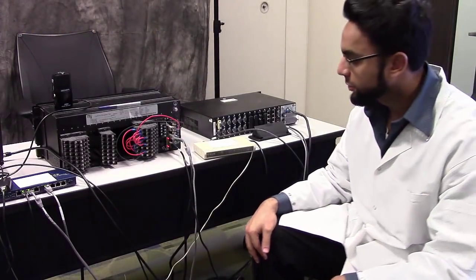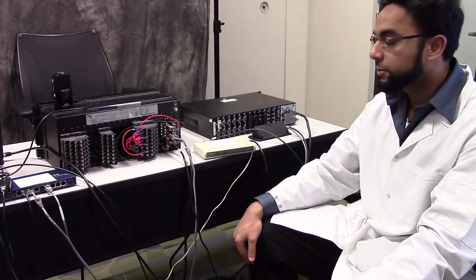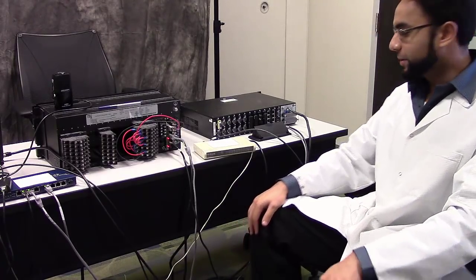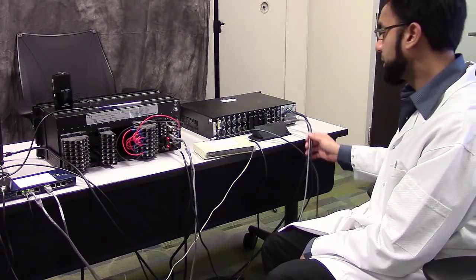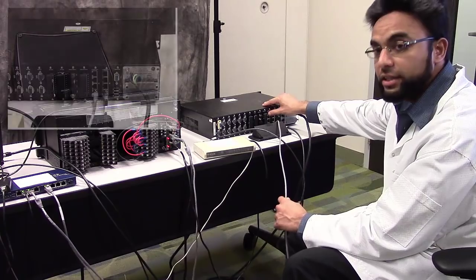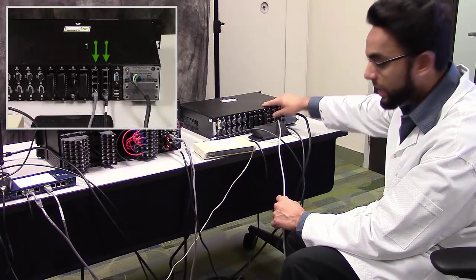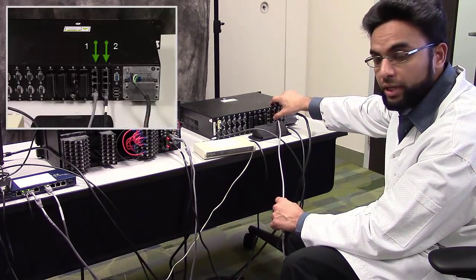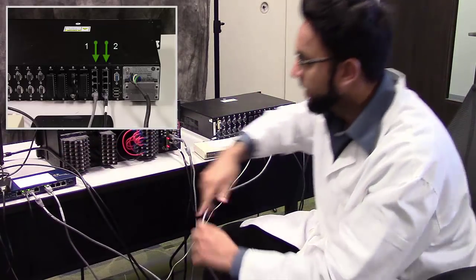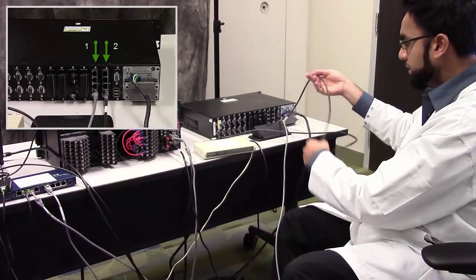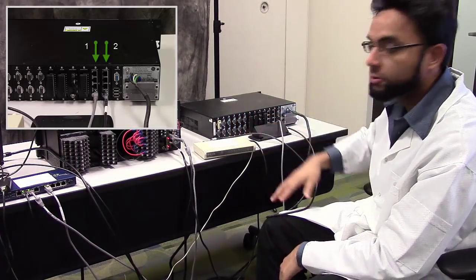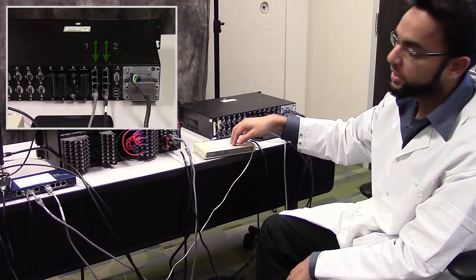Okay, now I'll show you the physical connection, how the D400 and the UR are connected together. On the D400 you have two Ethernet cards. This is Ethernet card 1 and this is Ethernet card 2. Ethernet card 1 would be connected to switch 1, and Ethernet card 2, which is LAN B of D400, is connected to switch 2. So switch 1 is LAN A, switch 2 is LAN B.